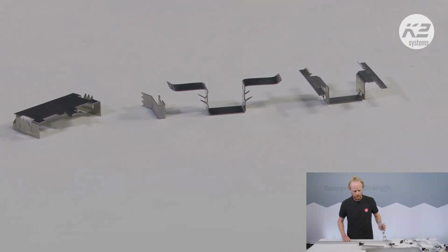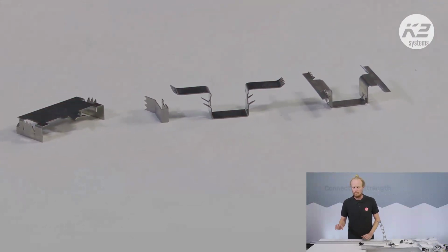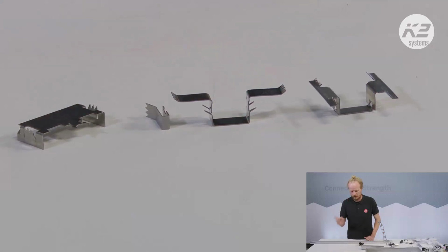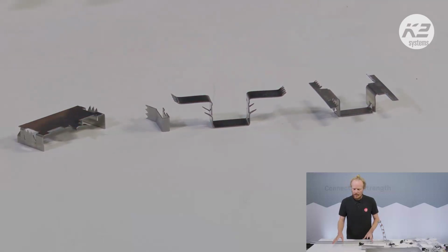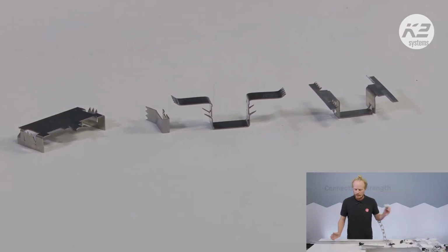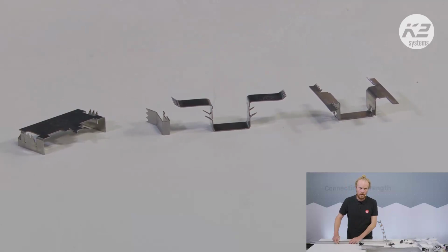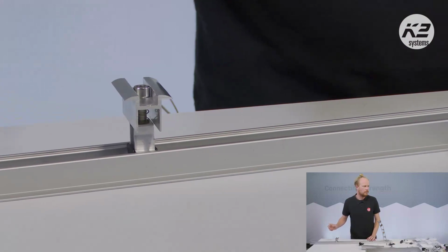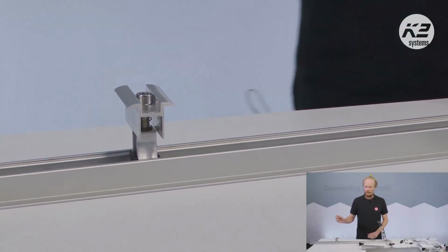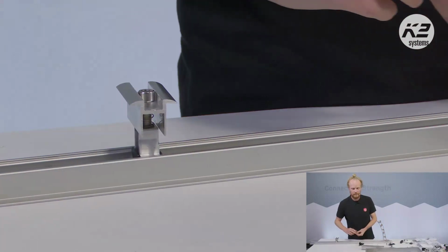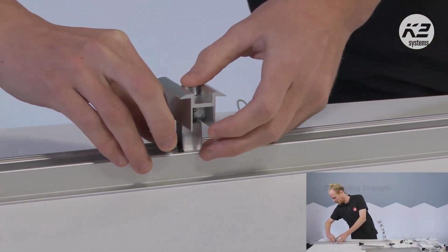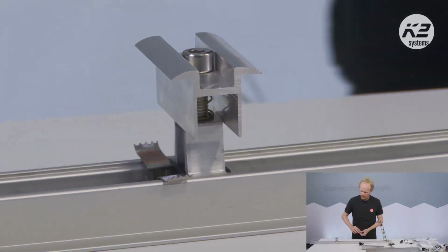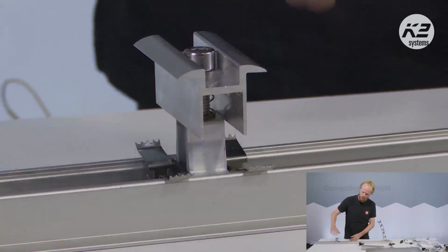The reason being that the aluminium and the module frames can build up an oxidized layer, and we want to scratch through that and ensure that there's a connection. So we have quite a different range, because we have a few different products, and one of them is used for our mid and ends, which I've just popped in here. So this is our K2 SZ, and for our middle clamps, they're just going to sit on either side, and generally speaking, we need one of these per module.